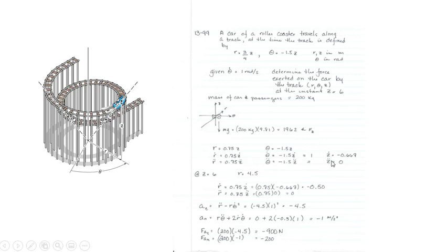Since that's a constant, theta double dot has to equal 0. So that's where we end up, and we want to make sure that we get our z dot. Then we can plug in when z is equal to 6 and solve for it, so we can solve for our tangential component, our normal component, and then our various forces.